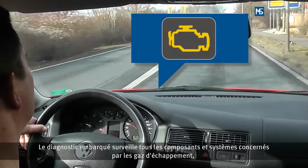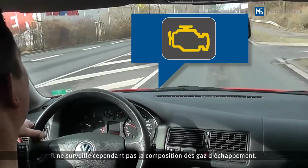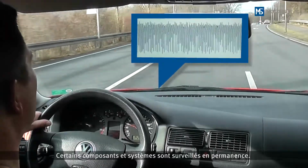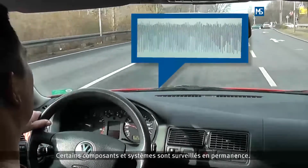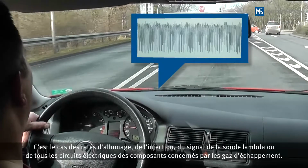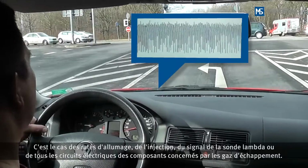The onboard diagnostics monitor all exhaust gas-related components and systems, but not the composition of the exhaust gas itself. Some components and systems are permanently monitored. For example, misfiring, injection, the signal of the lambda sensor, or all circuits of the exhaust gas-related components.